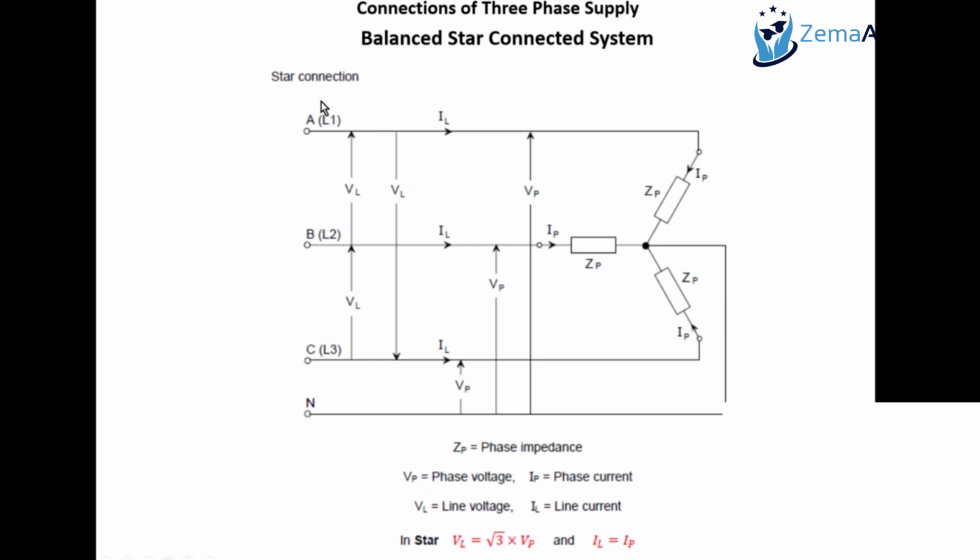So we have three separate line voltages, and the line voltages are different to the phase voltage, because the phase voltage means the voltage across the load. We call it phase voltage. So there will be three phase voltages, and the phase voltages, like the 230 volts that we receive from mains power circuit, has the phase and the neutral.